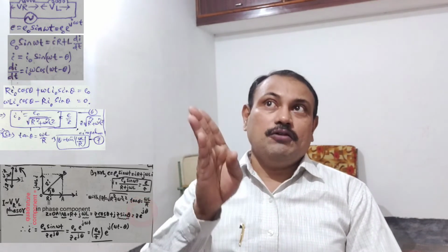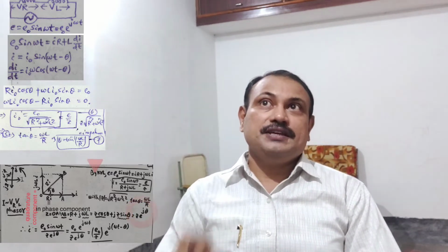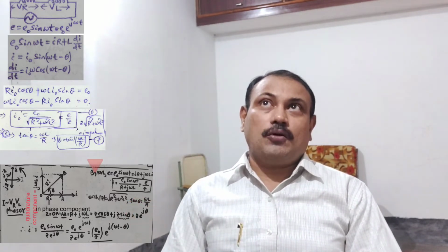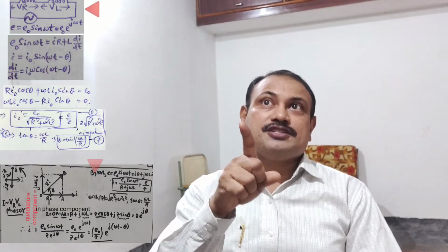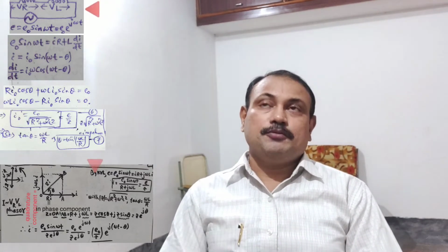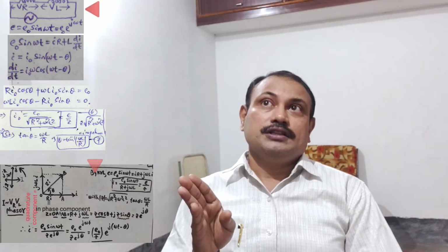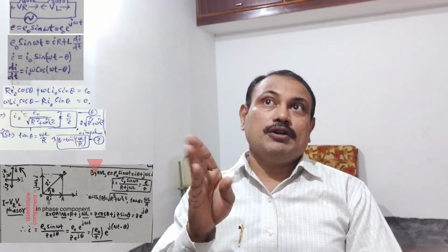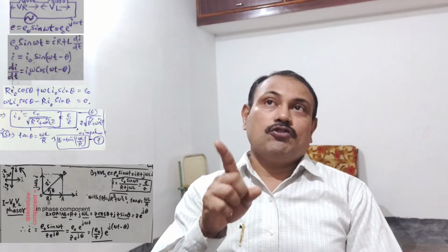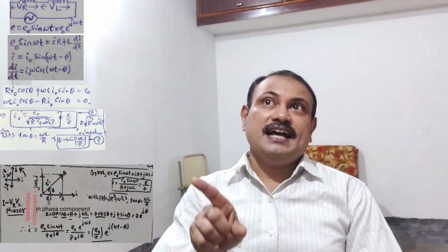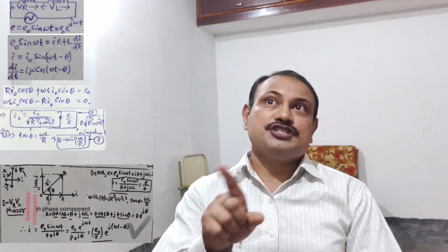So now we can directly write Kirchhoff's voltage law by looking at the diagram, that is E equal to IR plus J omega L into I, being the potential drops. So I will be equal to E0 sin omega t upon R plus J omega L, where I can also be written as E by Z, and Z being R plus J omega L.